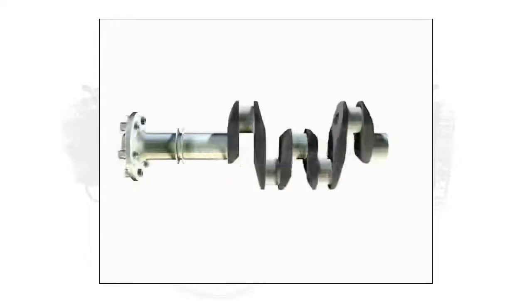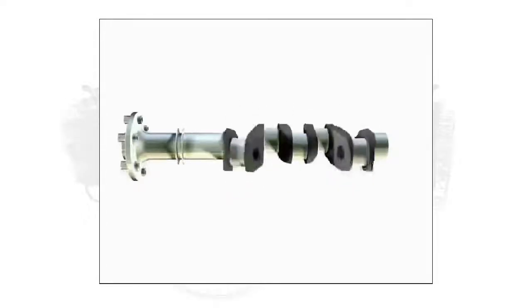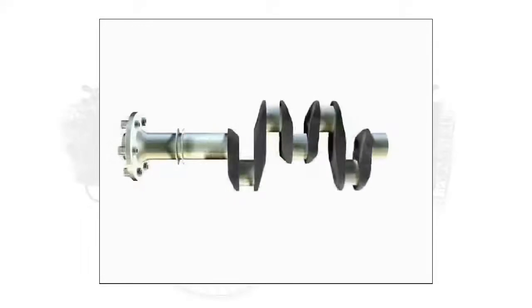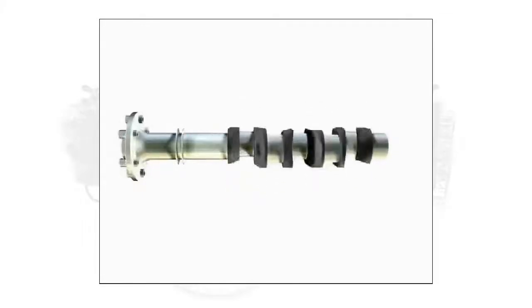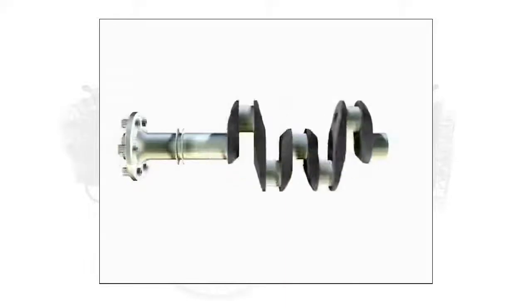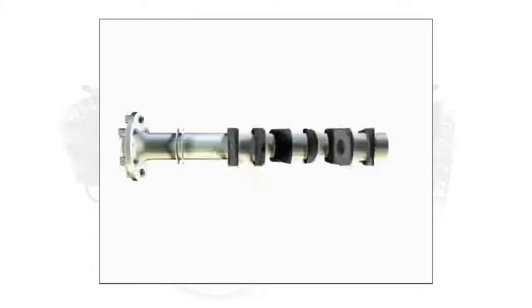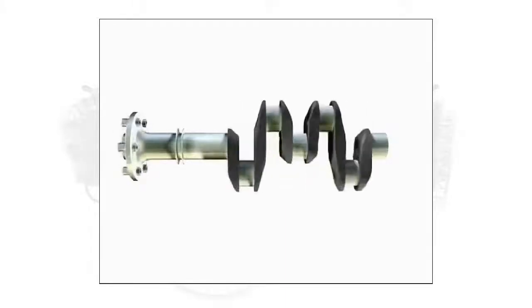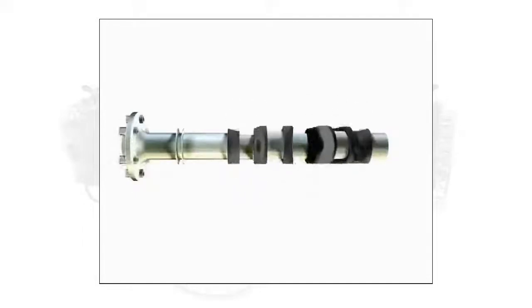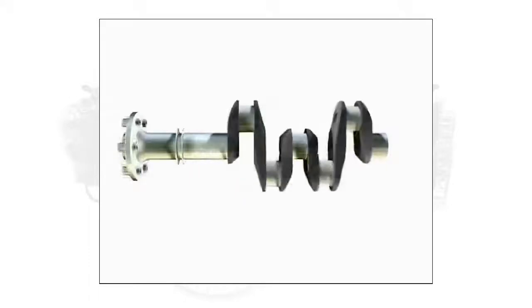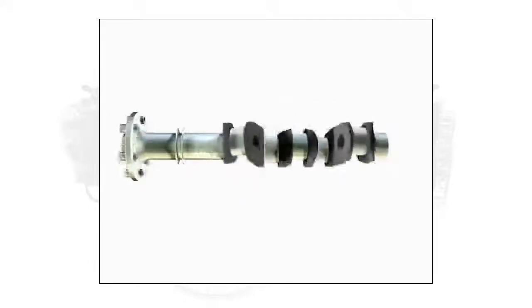The repeated applications of force to which the crankshaft is subjected may set up oscillations as the shaft recovers its original shape between power impulses. At certain speeds, the impulses may coincide with the natural vibration period of the shaft, and give very rough running, even in an engine mechanically balanced.